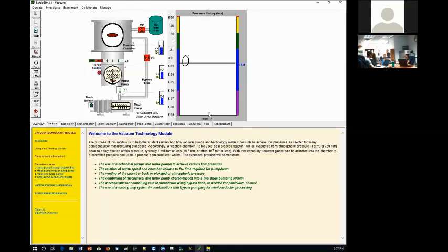The conductivity of the mass transport of the gas inside is going to be low. It's going to take time. Does that make sense? Whereas look at the turbo pump, the high vac valve, that portion, the radius is large, very large. You guys see that? So it will pump it down very quickly. Okay? But you never do this, okay?